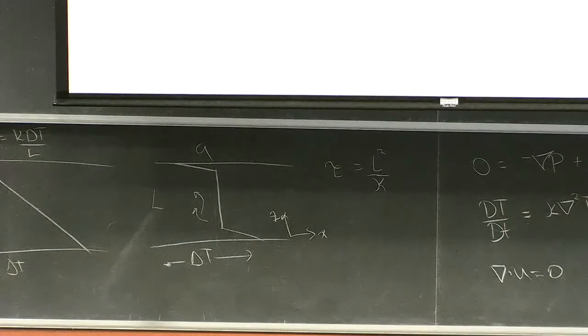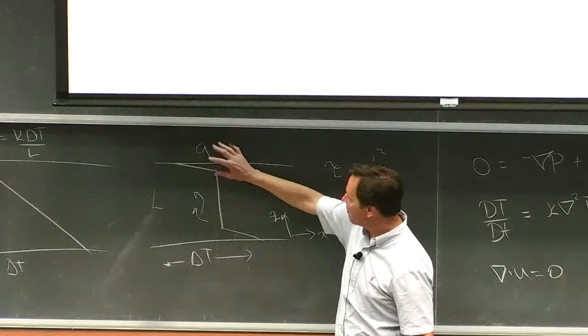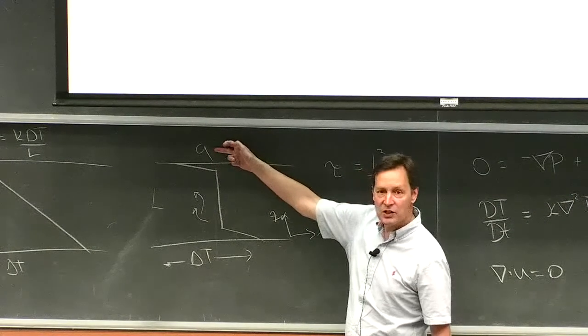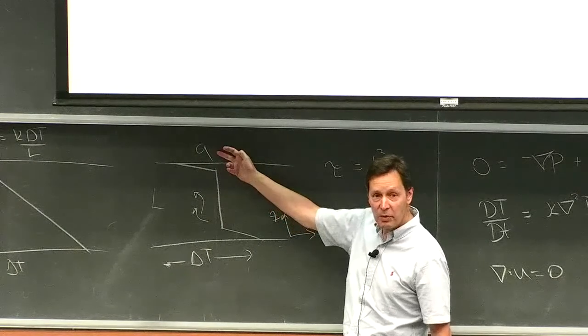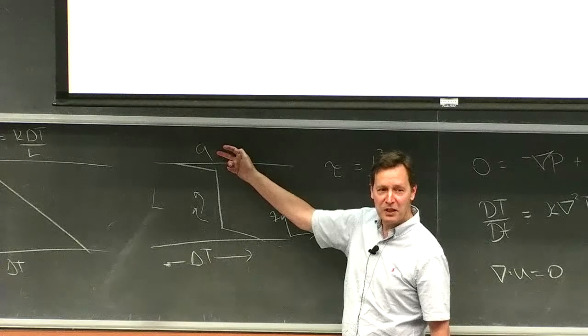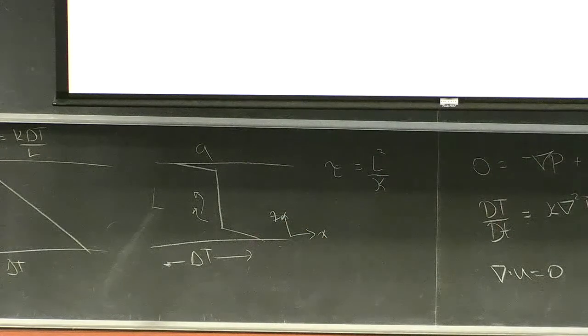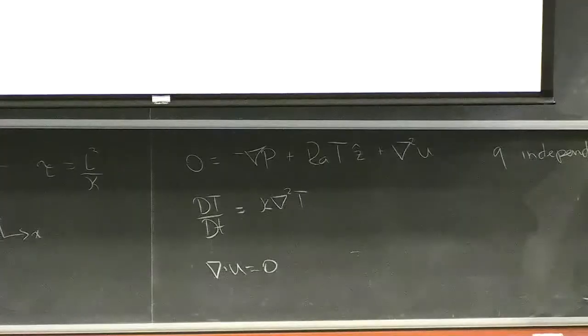If I make the assumption, the only assumption I make, is that the heat flow is determined by just things that are going on in the vicinity of the boundary layer structure, that this physical heat flux is independent of L, I'm telling you that I've completely specified the convective system and can predict almost anything. And it's kind of neat. Okay, let's see how this works. So I'm saying that Q is independent of L, by virtue of it being really a boundary layer process.